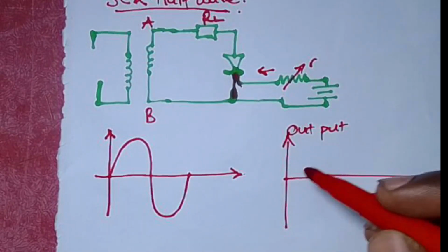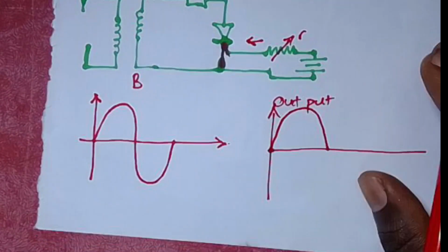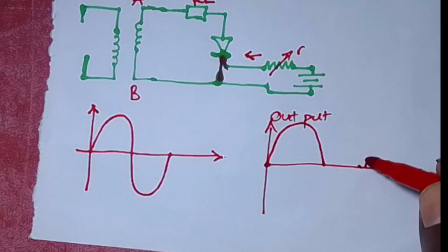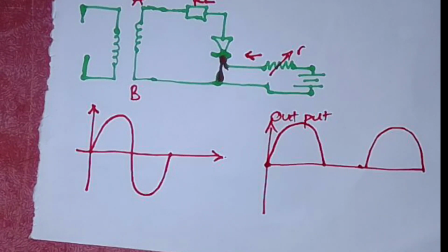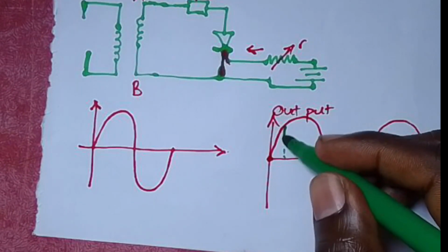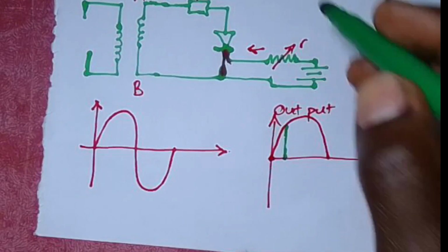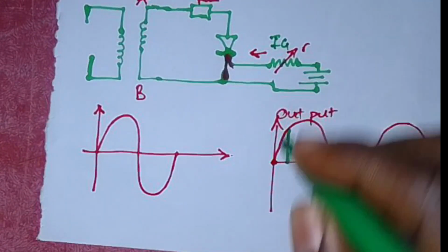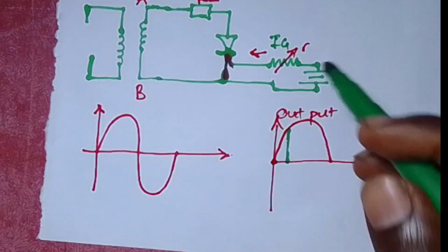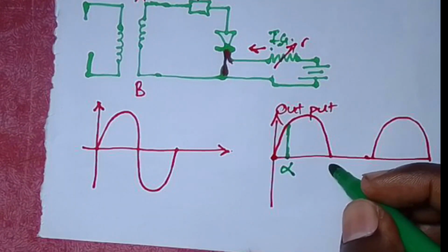But what I wanted to explain is simply the conduction angle. Because this is a controlled output, there is a reason why it is called an SCR. The output of an SCR will not be there, even if the input is positive, until the gate current is at a certain value. So by varying this gate current, we vary what we call the firing angle.